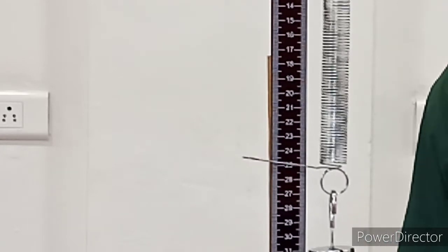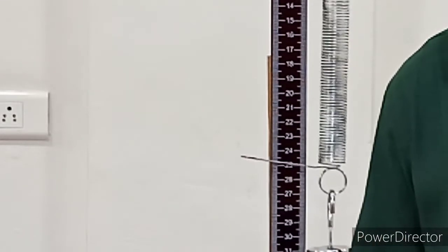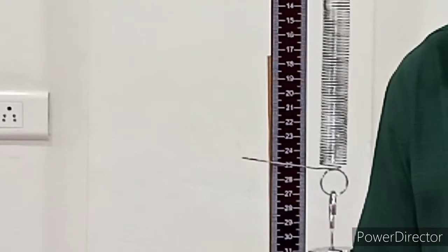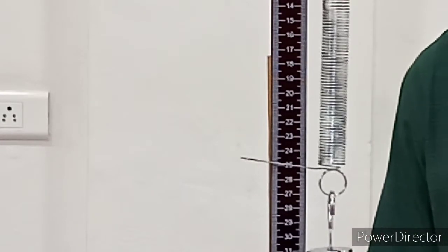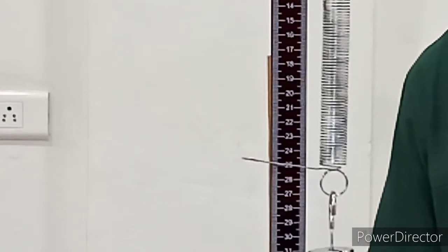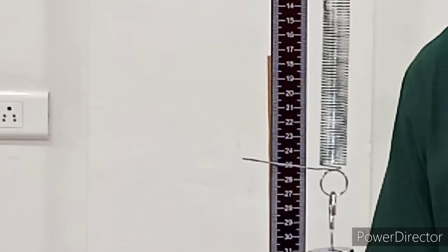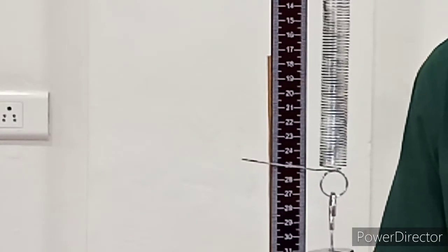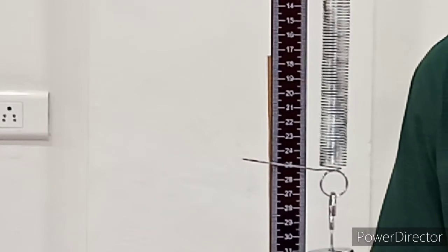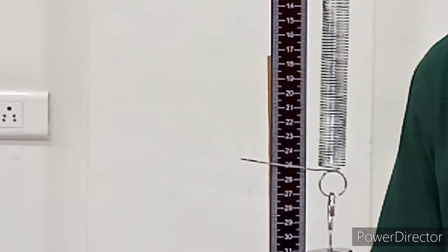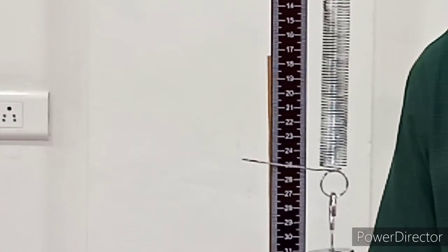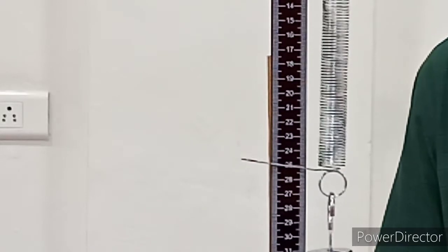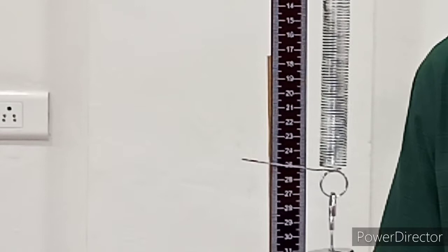So, I have noted the readings under the column loading. Now, the same should be repeated for unloading. In the loading column, we started from the dead load and ended with the 250 gram weight. Now, the reverse we are going to note down. The last reading of the loading column will be the first reading in the unloading column. Understand? Same reading only will be written on the right side. I will show you by writing on the board.